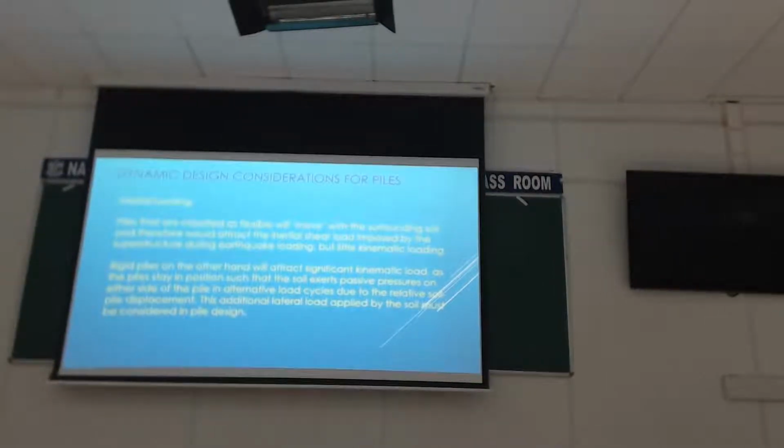Now, this definition of flexibility is important because in terms of inertial loading, if the piles are classified as flexible, so they will move, then you will attract all the shear load coming from the inertia of the building. The soil won't do anything for you because you're moving with the soil, and your pile has to carry the shear all the way down.